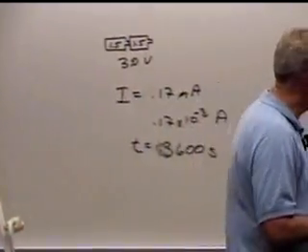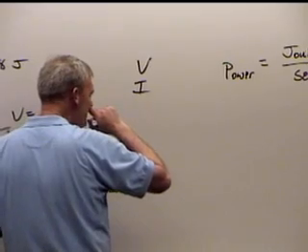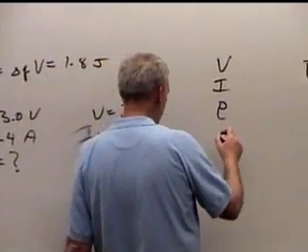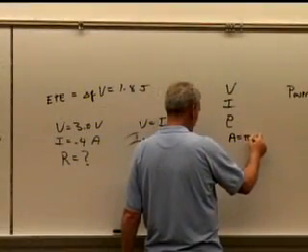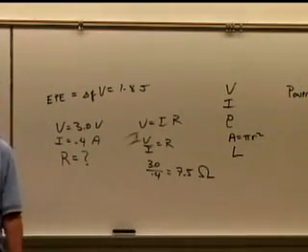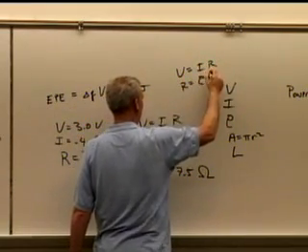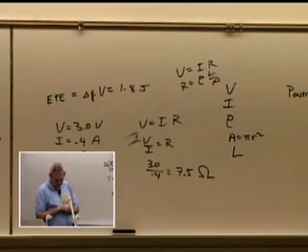In other words, you're given V, you're given I, you're given rho, because you can look that up, and you're given the radius. So you're given A, which is pi r squared. You're given all that. Can you figure out L from this? Yeah, because you got V equals IR and R equals rho times L over A. Okay? So it's right there. That would be problem 18. Just so you get kind of used to doing that kind of thing.